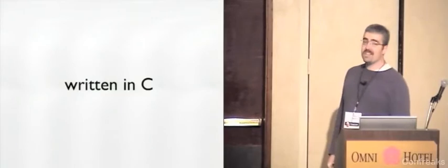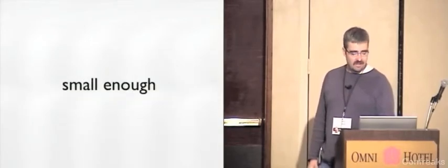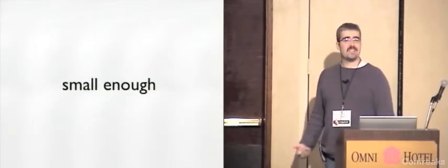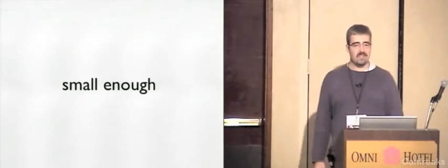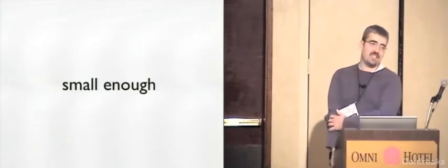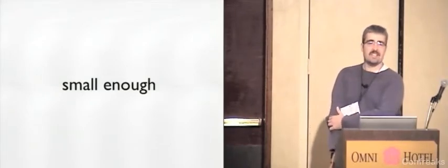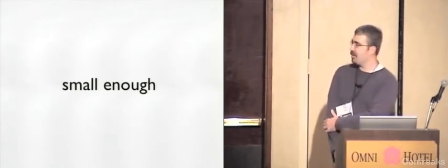And our other target we had was a unit test written in C. We wrote a little C test library called Unity. The reason for that was it had to be something small enough. We found CPPUnit was way too big for what we needed. We actually could have tried switching to a C++ compiler for this project, but that would have left us very little memory left over in this board.